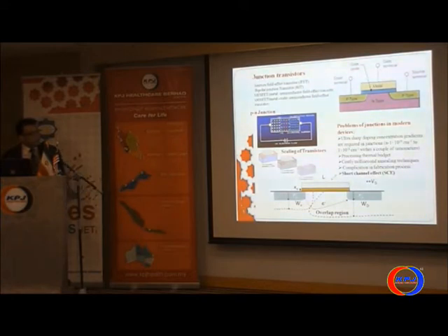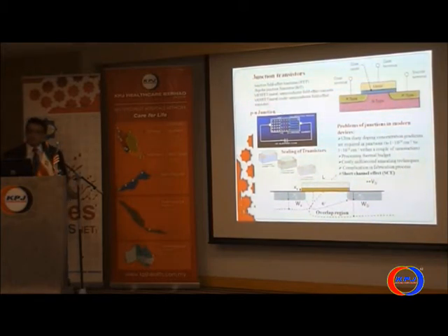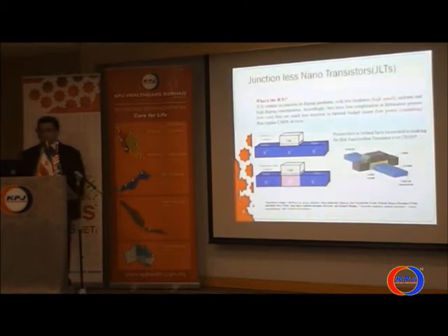Second, the processing thermal budget, the costly millisecond anneal, because when the size is smaller, we cannot anneal it easily. For activation, we need to heat the device, and when the size is so small, this heating is tricky. We have to control this heating part, so it's really costly. And the last but not the least is the short channel effects. Short channel effects means this overlapping between these two junctions, which really limits the performance of the device.